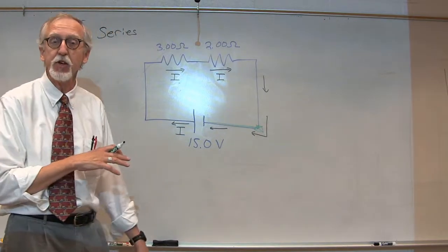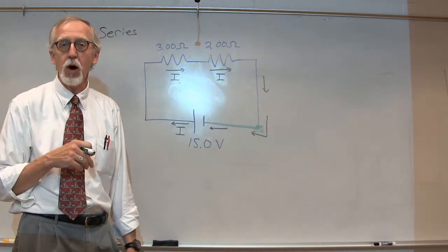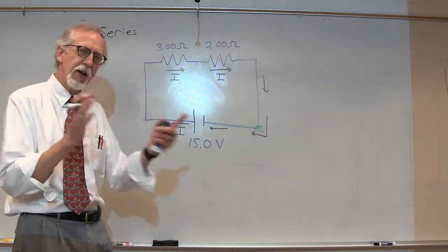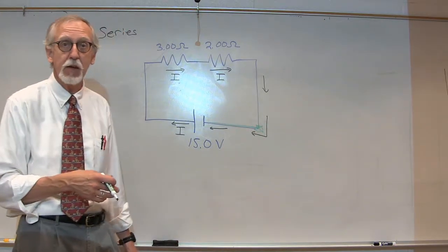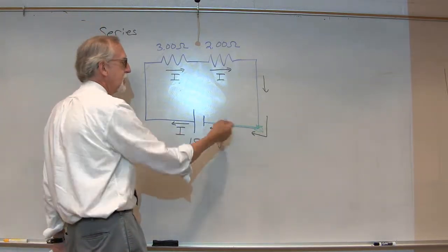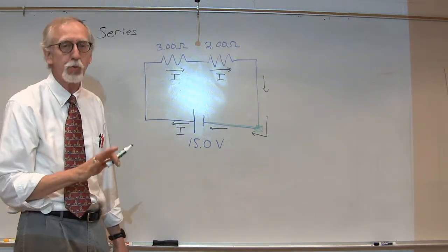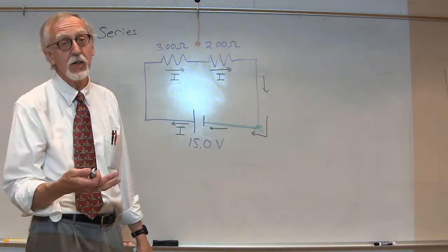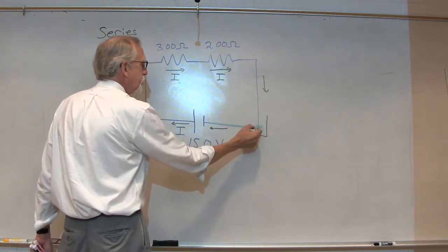Now, if you'll remember the calculation that we did earlier when we looked at the resistance of a very, very long piece of copper wire, 100 meters long with a diameter of 1 millimeter, we found just a couple of ohms. So for any short wire, something you might use in a circuit in lab, or if you wanted to make something at home, probably you're going to use a much smaller wire, probably with a larger diameter. And so the resistance of that would probably be insignificant compared to any resistances that you might have in the circuit. So that's what we're going to assume. We're going to assume that the wires have negligible resistance compared to anything else in the circuit. So, no change in potential, no change, no change.